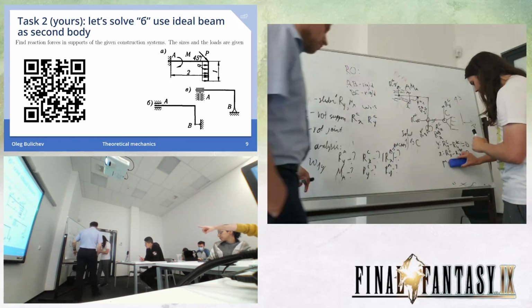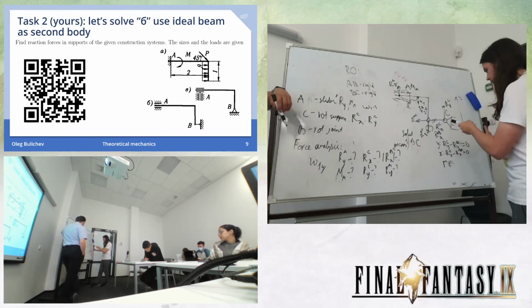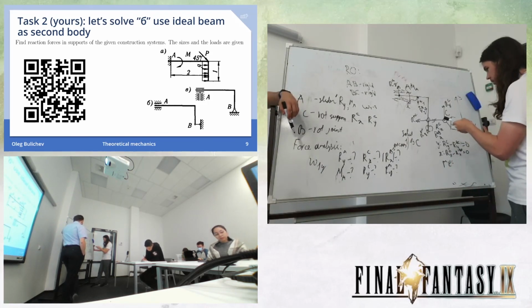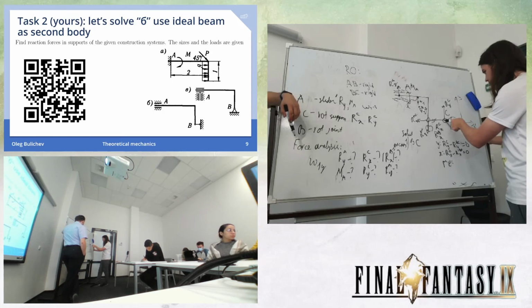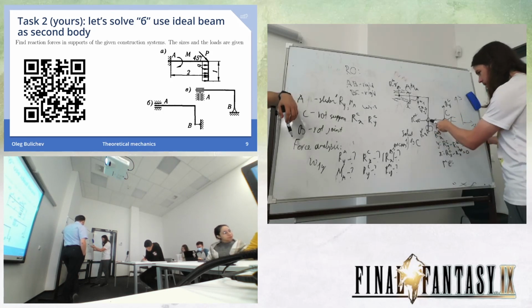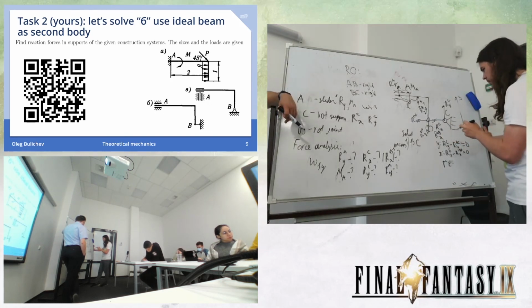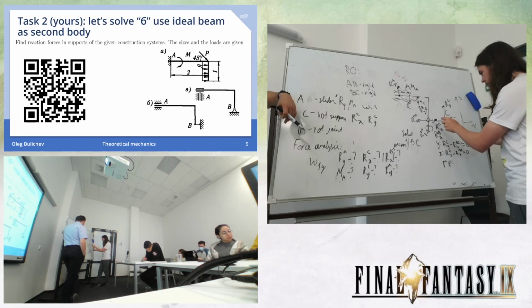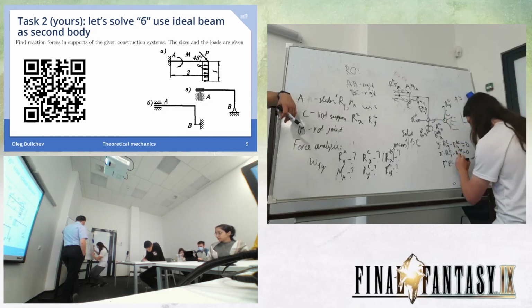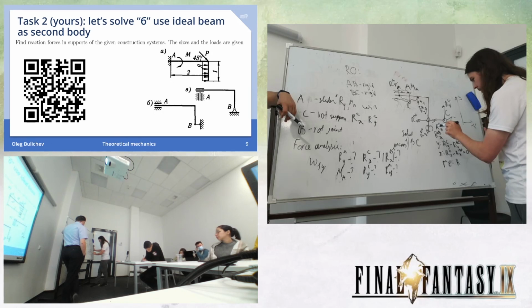We assume the direction of the reaction to be some arbitrary direction here, because this length also affects this point. So it pushes, but at an angle. It doesn't push only from the side. It makes sense to think about it like pushing from the top, but it has some angle. So the direction should be at an angle, and we just analyze it by projecting it. Same here.